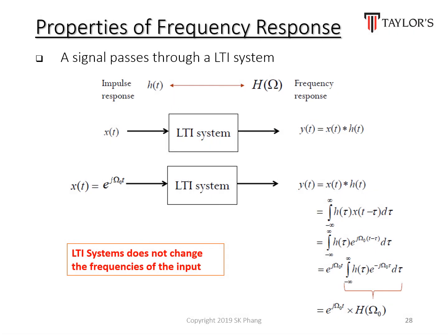Alright, so you have already learned how to compute the Fourier series of given any signal or any systems. So next is how do we use it? So if you remember in the last chapters, when you learn about convolutions, if you have a signal in time domain that passes through a system, if a system is given to you the impulse response in time domain, your final answers, the output, will be just the input convolute with the systems.